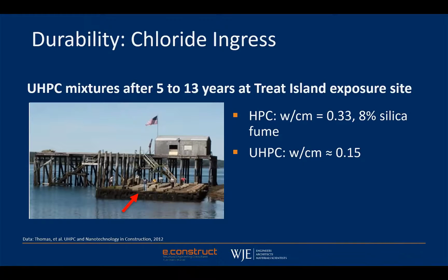And so the samples included the 2 mixes that are identified on the slide. First, a high performance concrete, an HPC, with a water cementitious ratio of about 0.33, 8% silica fume. So certainly not a slouch in terms of a high performance concrete. And then the other samples included ultra high performance concrete with a much lower water cement ratio.